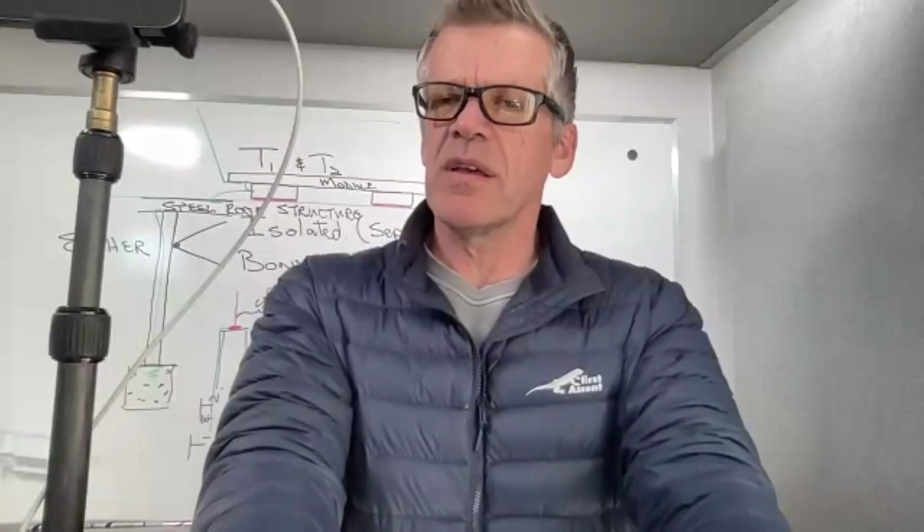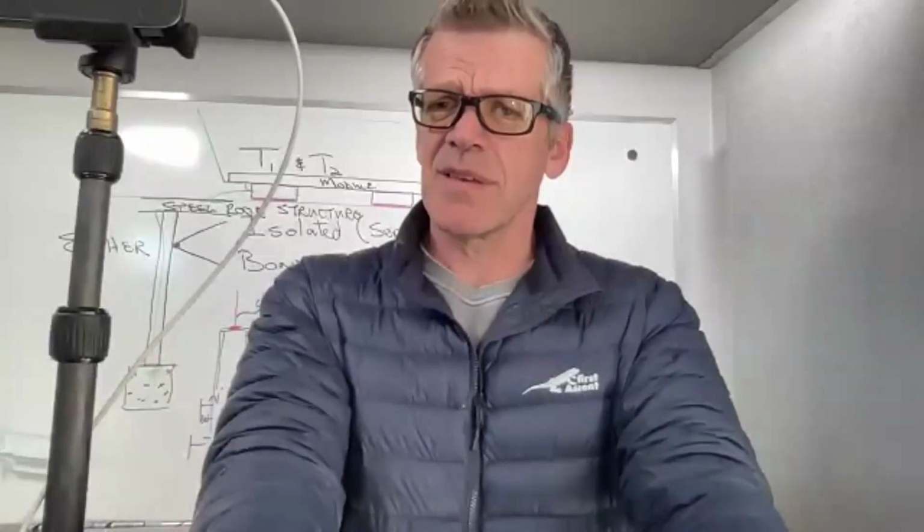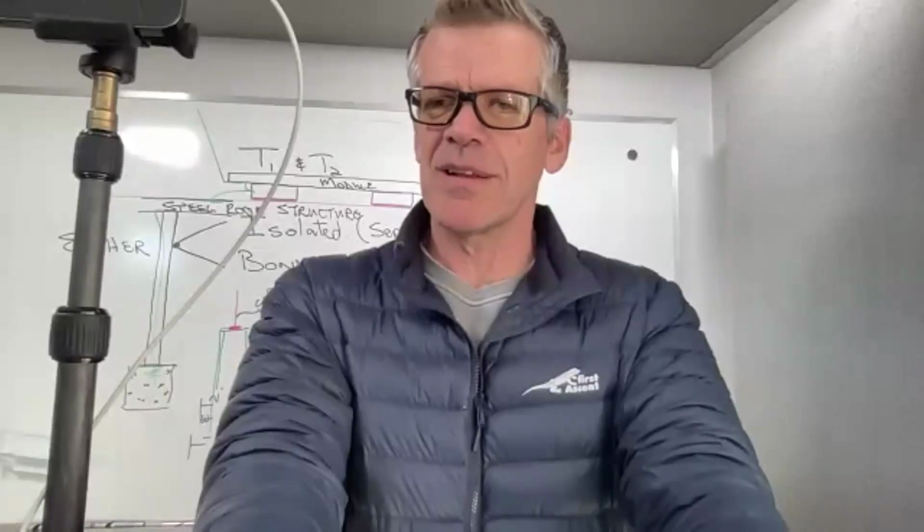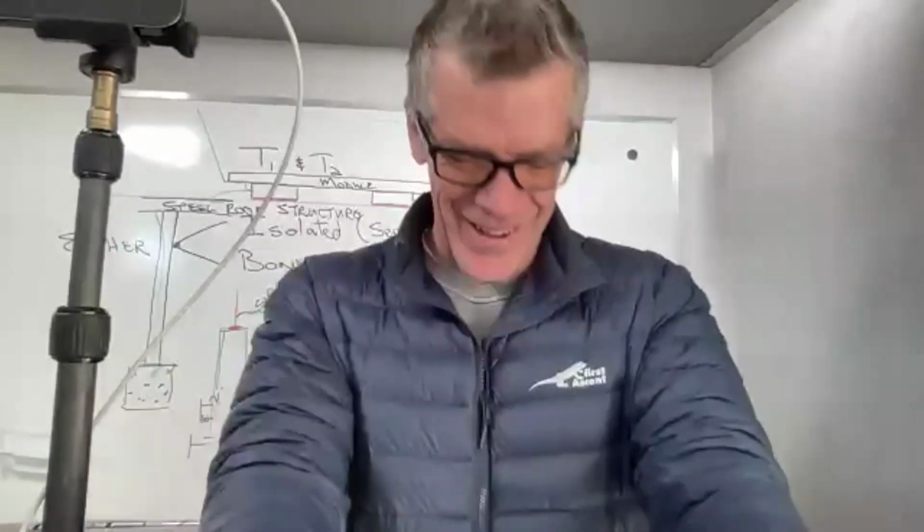So really, yes and no, as Kenneth would say, theoretically and technically, that might be different. So I can maybe clarify that. A surge protector can only handle surge. It's a waveform that is 8x20, and lightning is 10x350. So lightning and surge are totally different types of beasts, let me call it that. So it's not the same.